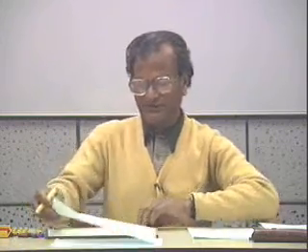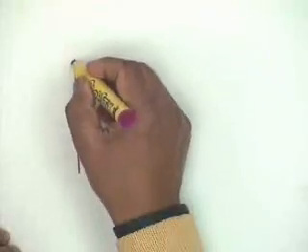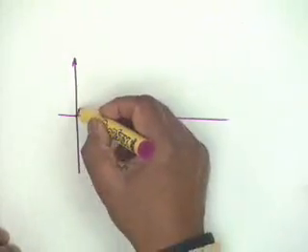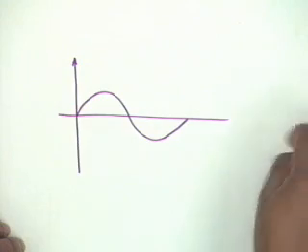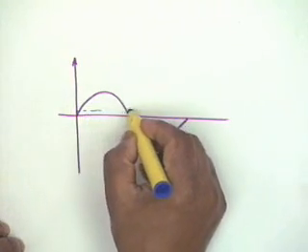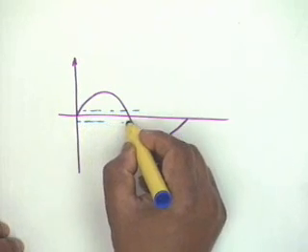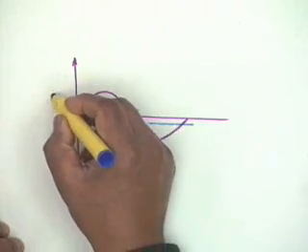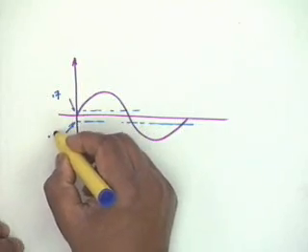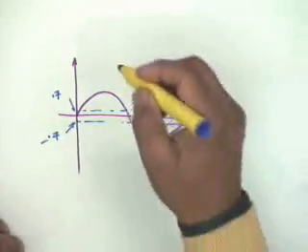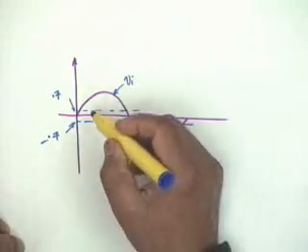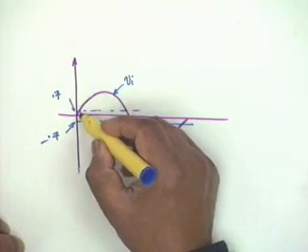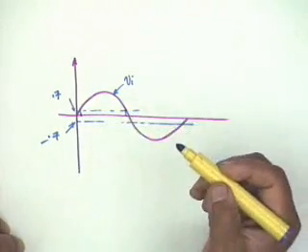And obviously what we will get if we have a sinusoidal input, like this, and if these lines are 0.7 and minus 0.7, we take VBE on as 0.7, and this is Vi, then V0 would start here and end here during the positive cycle.